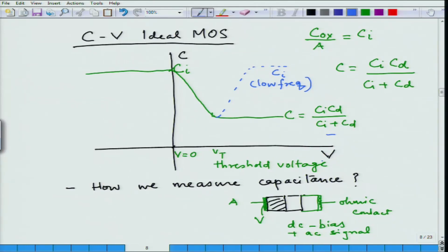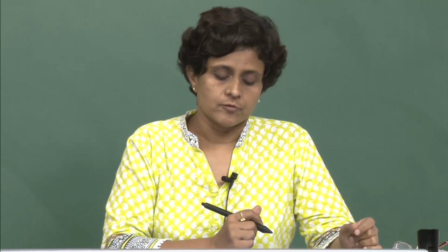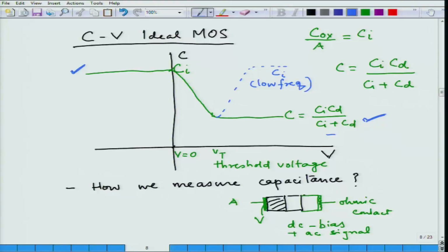I apply. I can have a state of the device where it is at this capacitance, and I can have a second state of the device at higher positive voltage where the capacitance is different. And you can start seeing its use as a memory element already. So, depending on what voltage is applied to the device, it will work as a memory element. So, having done this